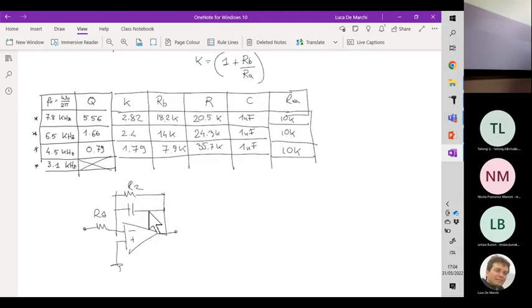So this is how you implement a first-order active filter. In particular, this filter's angular frequency is controlled by the product of the capacitance C with the resistor R2, while the DC gain of this configuration is equal to minus R2 over R1.